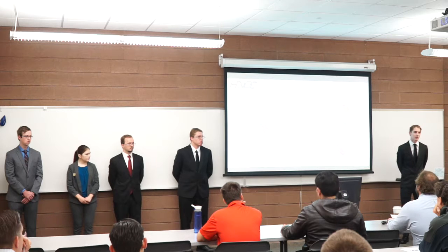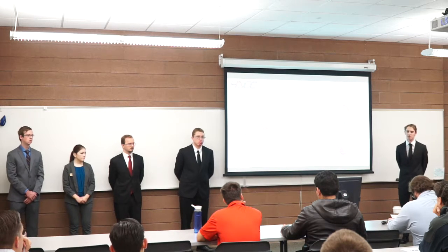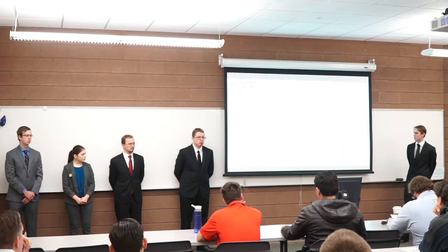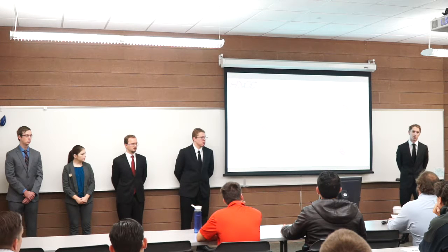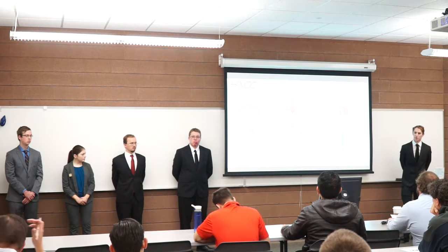The middle phalanx is very similar. It's basically just a smaller version. There's only 1 bolt in there. But again, the passageways are the same. There's 2 phalanx covers that sit over it. The backbone is threaded the same as the proximal phalanx.